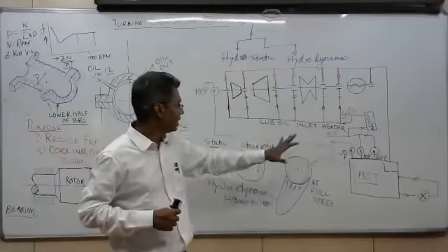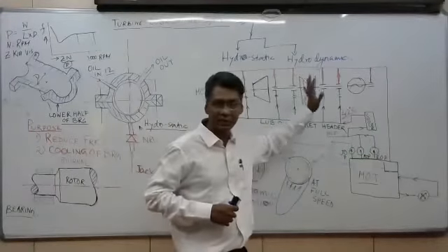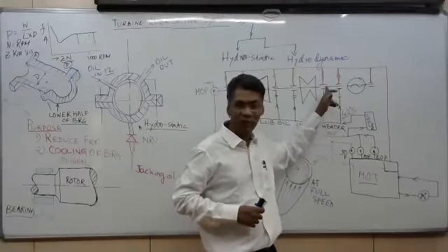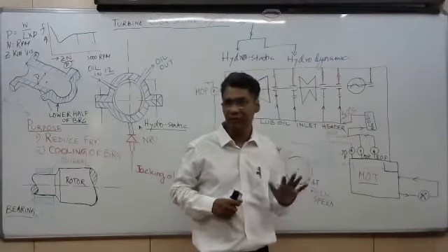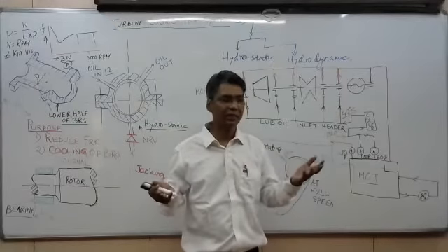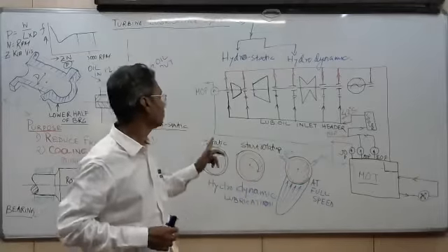So oil is coming, and that is the lube oil scheme of the turbine system. The emergency oil pump provides oil in an emergency so that bearings are not damaged. Once a bearing is damaged, removing and replacing it means a shutdown is required. It is a very long process, so we have to be very careful about the bearing.